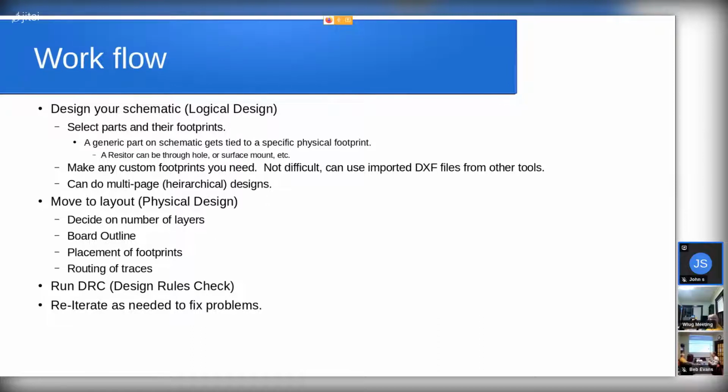When you design your PCB board, a lot of people try to design it to look exactly like either the breadboard they built it on, or exactly how it's going to look when it comes out of the PCB. The idea behind the schematic is to break your design up into logical blocks, a logical layout, so that you can have a power supply on one sheet, or in one corner, and your interfaces. So the idea of a schematic is to give a logical, higher level overview of your design and how it's put together. There's an art to doing a good schematic. I am not an artist.